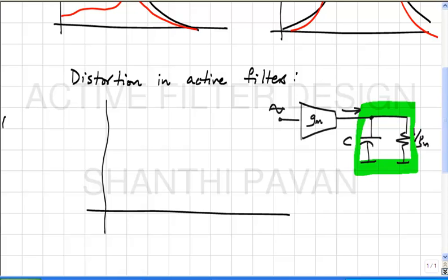the impedance. So one thing that you can expect is that at very high frequency, the capacitor will suck up all the harmonic current and the output voltage will have relatively small harmonic content because the filter itself is filtering off the harmonics. And please note that when we talked about harmonic generation, we said everything is fully differential in practice. So really the most important harmonic you need to deal with is the third order harmonic, right? The third harmonic will be at 3 times higher frequency than the fundamental. So for example, if you were trying to measure or figure out how linear this filter is, does it make sense to put a tone at the band edge? Yes, no? Why?